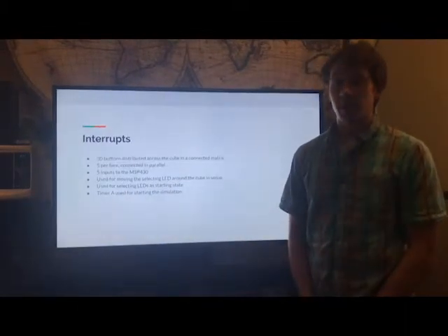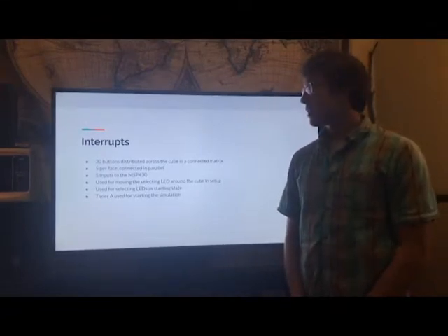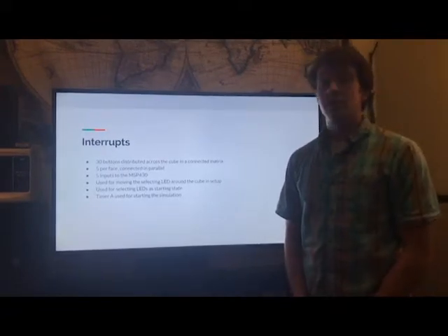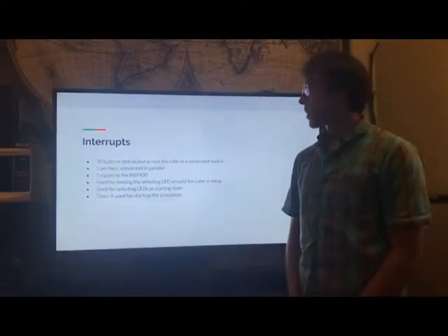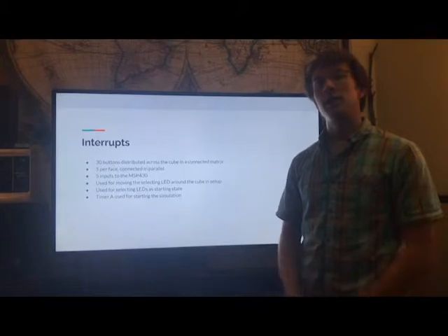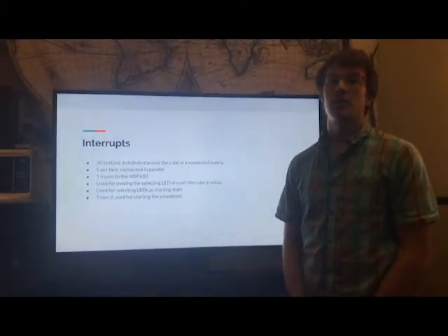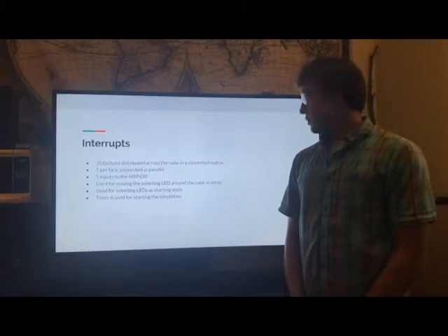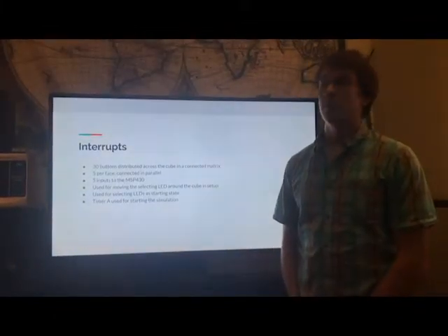Interrupts were really important in this lab. We had 30 buttons distributed across the cube, many of which were in parallel to deliver 5 different signals coming into the MSP430 as user input. We used interrupts to pick up whenever these buttons were clicked, and to use that in our control logic as to selecting the initial state of the simulation. We also had an interrupt for timer A to use as a counter variable.